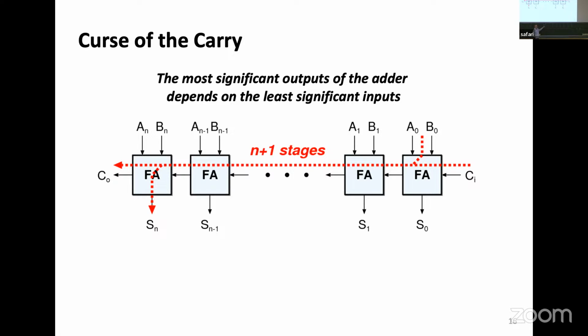At the same time, this guy is doing the calculation and says the sum is 1. There's no more sum, and the carry out is 0. The other guys the same way say the sum is 1. And at the same time, the first step, this guy says, okay, I have 1 plus 1. The sum is 0 and the carry is 1. So he's sending over the carry.